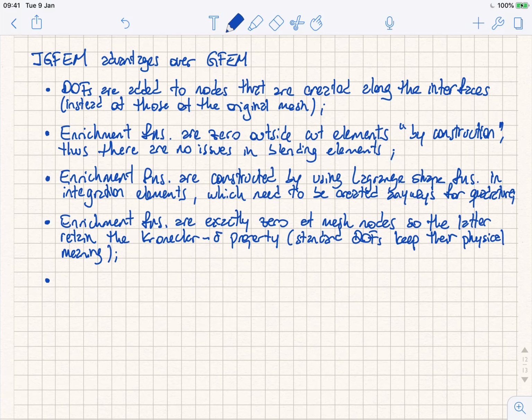The standard FEM can already reproduce the right physics because the entire approximation of the standard FEM is C0 continuous. So along that edge, you are able to reproduce the behavior. Yeah? So then the question is, what happens if your interface goes through only one node of your discretization, right? In some cases you can choose not to enrich there because you are relying on the standard finite element node being able to reproduce the behavior, right? But in other cases you have to, right?